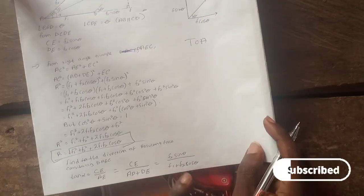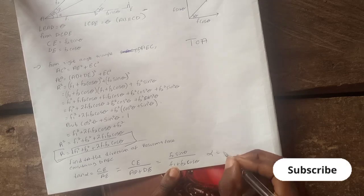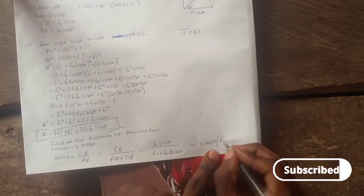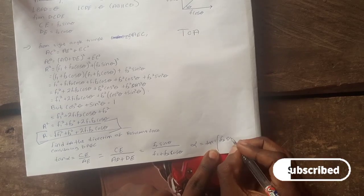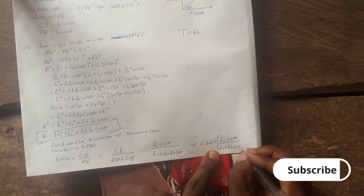Then we are looking for the direction, which is alpha. So our alpha is equal to tan inverse of F2 sin theta over F1 plus F2 cos theta.